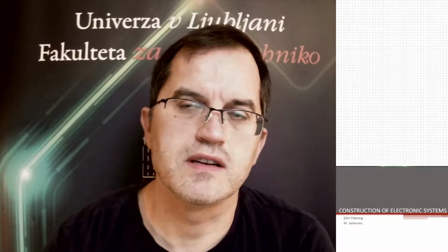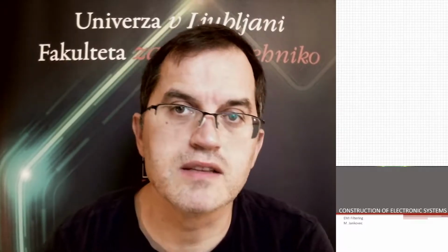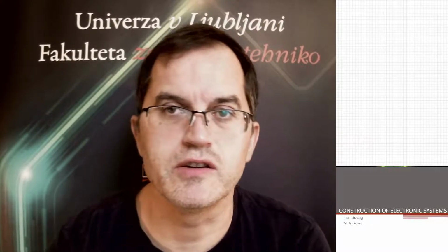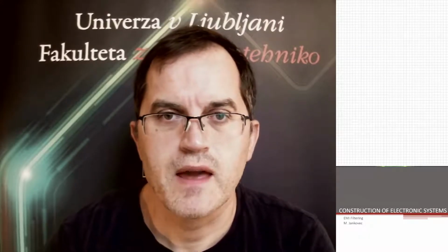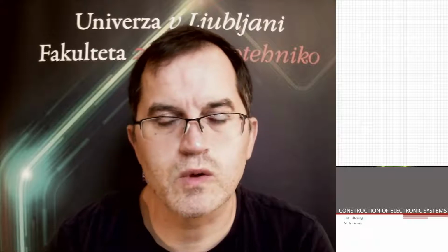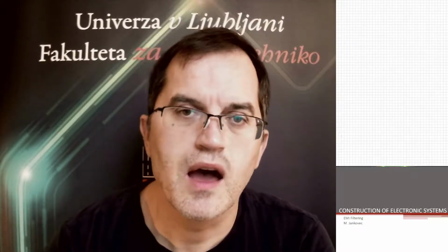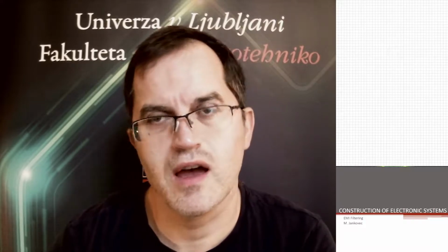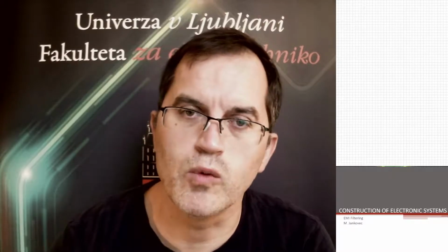Till now we discussed the EMI sources in PCBs. We discussed the common mode and differential coupling, coupling through common impedance, coupling through the air, which could be in near or far field. So several issues regarding the EMC. Then we discussed what are the main sources on the PCBs in electronic circuits, and we wanted to minimize these noises by decreasing the loop areas and also decreasing the areas of the signals which have high voltage changes.